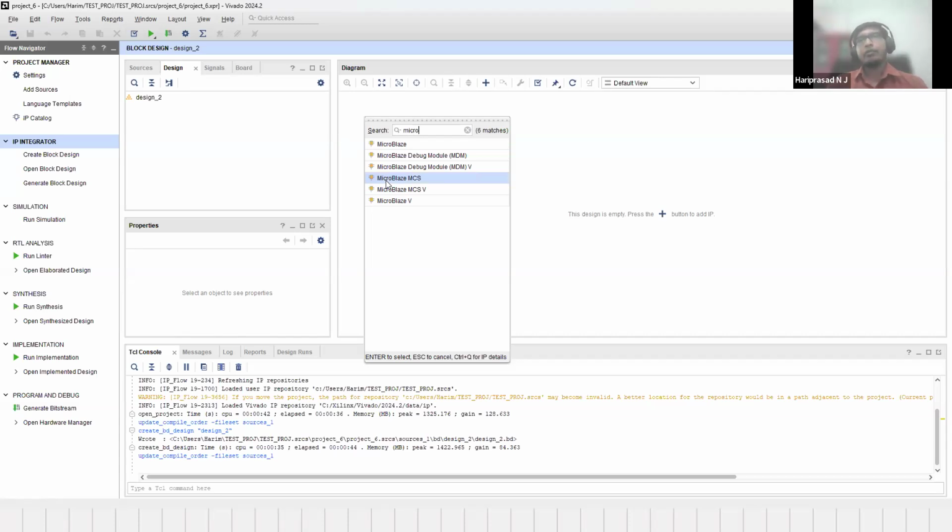Now, why do I need a controller inside the FPGA? The FPGA can perform all the operations, but again the resources matter. Let's say I want to build SPI, I2C and six or seven interfaces, and these are all for peripherals which are very low speed applications. All these seven interfaces I can fit as software code inside the microcontroller or microprocessor I implement in the FPGA, and this microcontroller as a master can control all the peripherals.